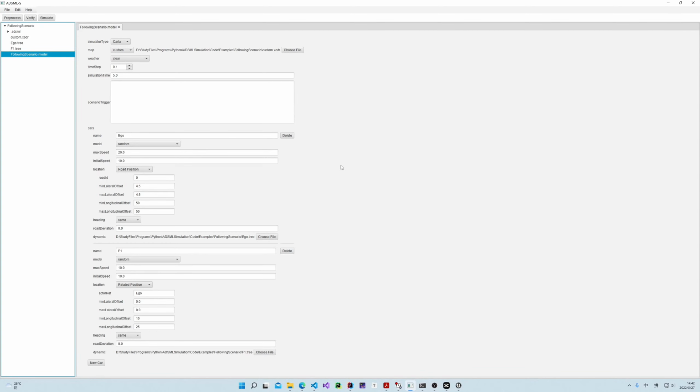In the Scenario Parameters Editor, a file selector is provided for users to import custom OpenDRIVE map files, which is very convenient for designers. Of course, it is also possible to use the simulator's built-in maps. We designed the drop-down box and other easy-to-use ways to configure the scenario parameters. We built CARLA's vehicle model, weather, and other option lists into the tool in advance.